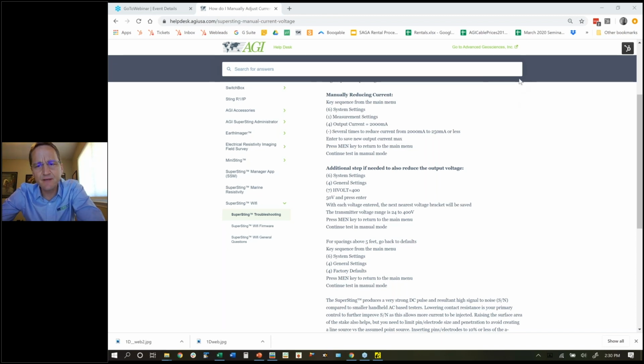And sensitivity is roughly 1/2 of your electrode spacing. That's for all methods. So your resolution is roughly 1/2 of your electrode spacing, and then lateral resolution needs to be 2D or 3D methods, and that's why I went into those slides at the end there.